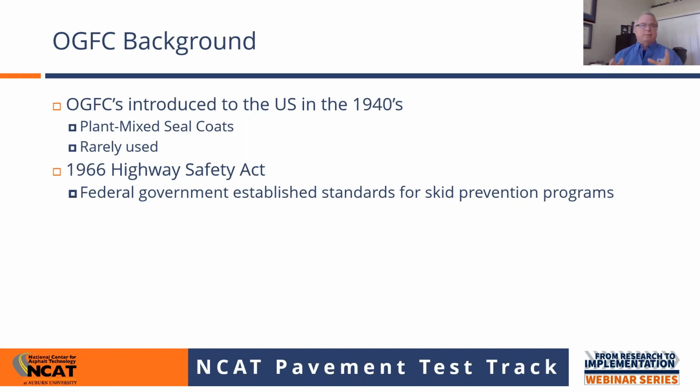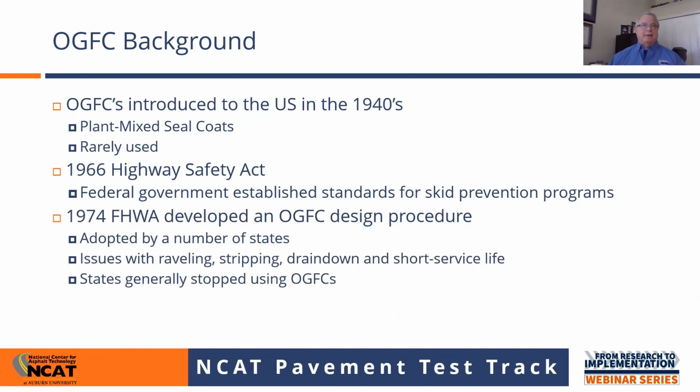But it was everything from guardrails to making sure you've got the right cross slope and super elevations, things like that. But it also established standards that told state agencies that they had to come up with skid prevention programs. And again, from my history with the Florida DOT, I know it was around the late 60s when they started experimenting with different friction course mixes and different aggregate types. A number of states started to use these open graded mixes. There wasn't a design procedure.